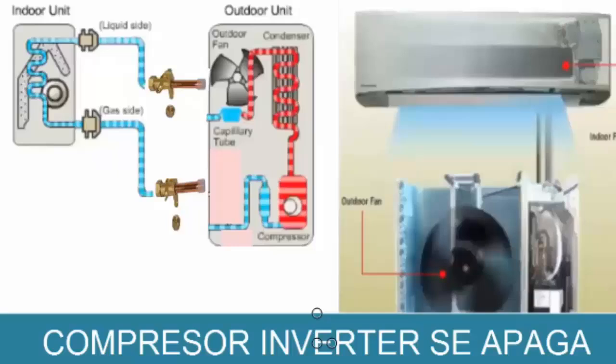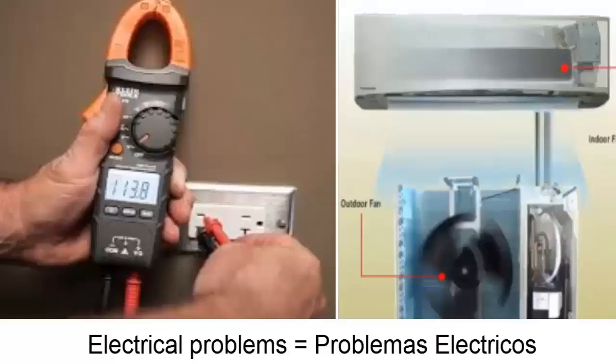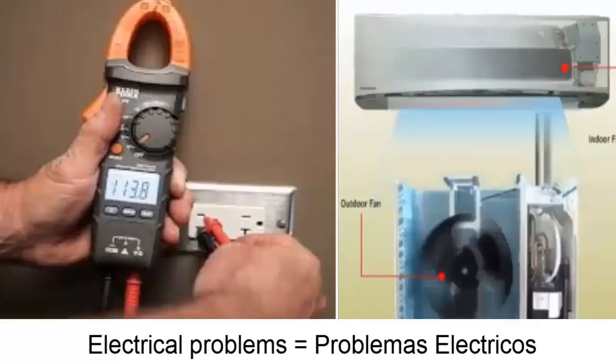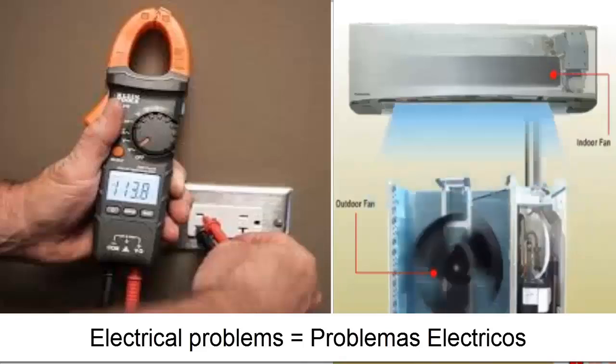Electrical problems. 1. Low voltage. Insufficient voltage can force the compressor to consume more current, generating motor heating. 2. Wiring problems. Faulty wiring can generate unnecessary electrical resistances that affect the compressor's power supply voltage.